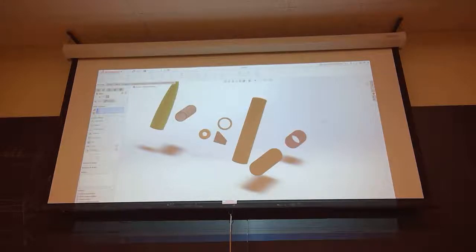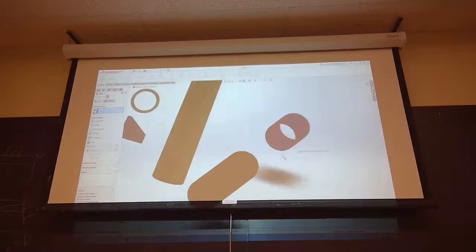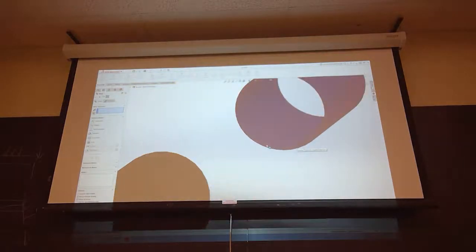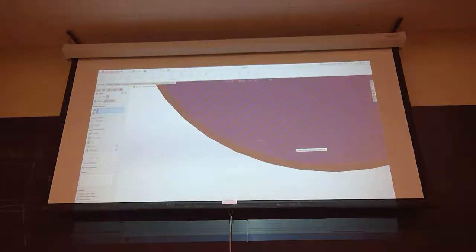And this time we're gonna mate two faces together. So the first one, you have to get really close because these tubes are thin, okay? You're gonna select this face. Now, really important, I guarantee half of you selected an edge. But you can confirm that by looking right here. It should say face 1, or might be a different number for you.